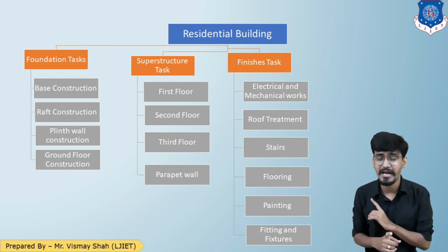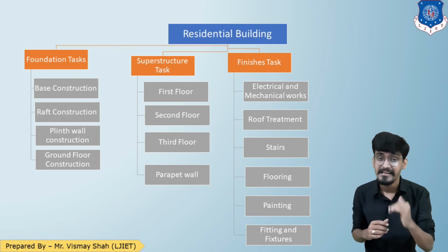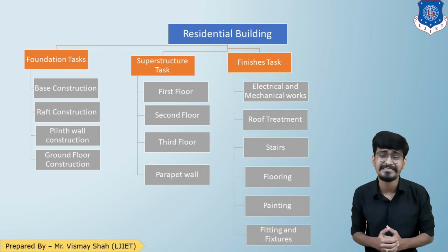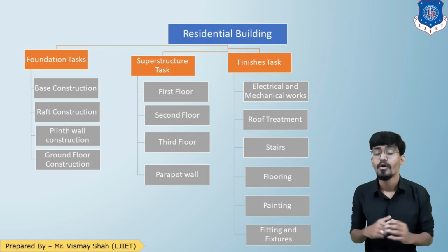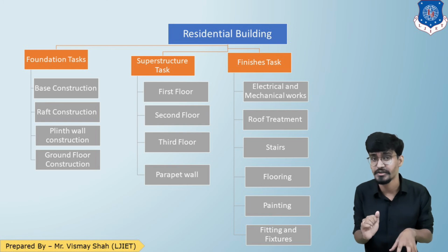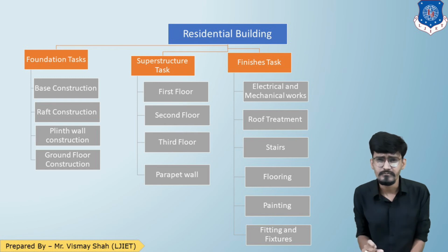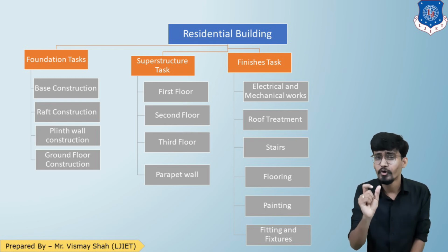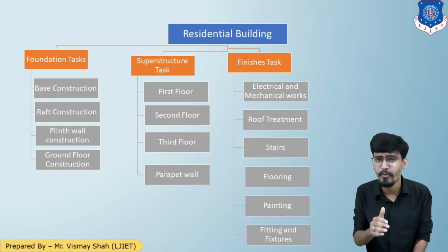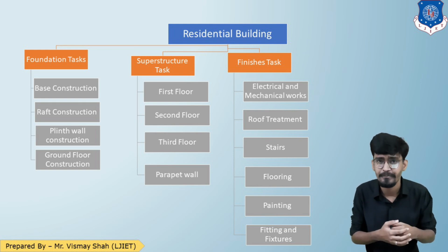So see students, here I have started the work breakdown structure from task level, then to work package level. It is not always necessary to start with the sub project level. You can start at any point you like. You only have to think about the activities and their interrelationship. I cannot put the work package of stairs in the foundation level, or put any component of superstructure into finishing. I hope you are getting my point, that you have to manage the sequence of the work.